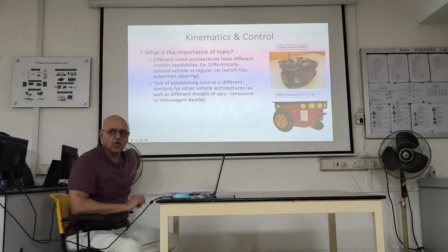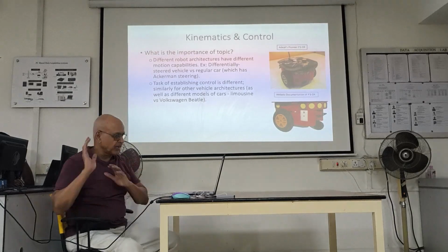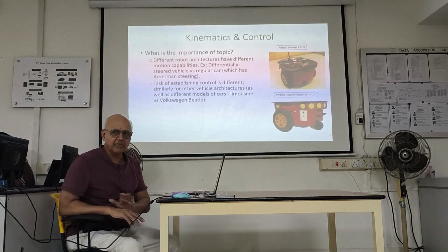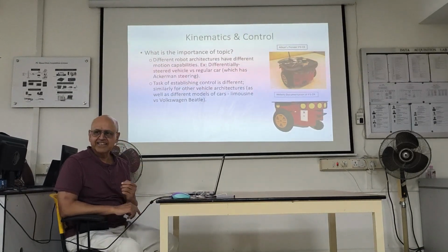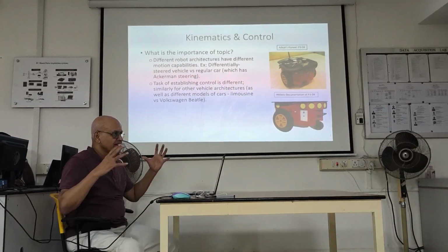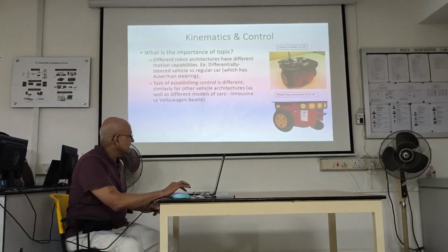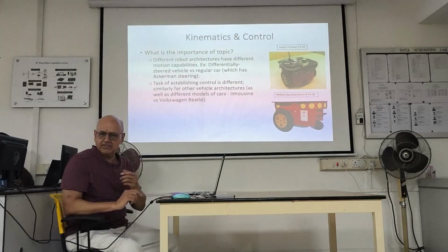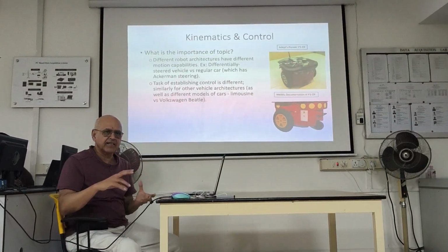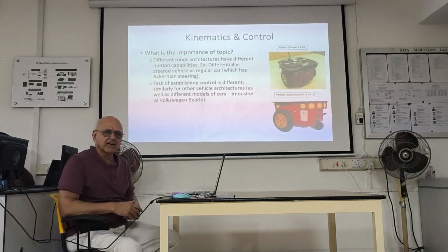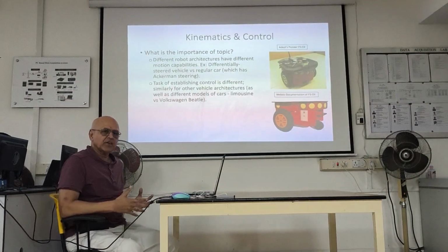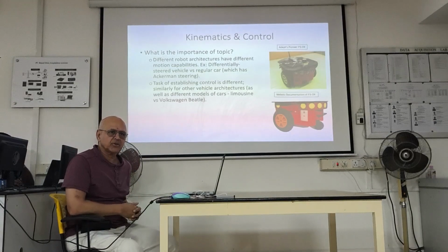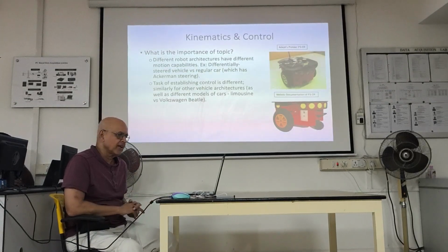So this robot rolls. Of course, if you hit it from the side, it's going to skid. I'm not talking about that. In normal driving, it rolls. Both drive tires roll, and the third wheel is a caster wheel. You don't have any caster chairs here, but normally it's the chairs with that flip-flopping wheel. So that wheel will do whatever the drive wheels ask you to do. It will come along. It's a passive wheel.